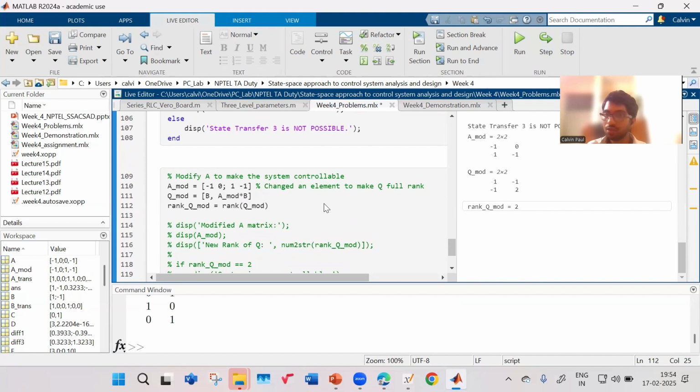First of all, you have to carefully observe the question. You have to understand the concept very well. Controllability means that the input has an effect on the state. If you write the dynamical equations, you can understand. Sometimes it is very complicated, and you don't know what has an effect on which, or it is not easy to understand. For that, they convert it into Jordan form. Once you convert it into Jordan form, it is easy to see which state is controlled by the input and which state is not controlled by your input.